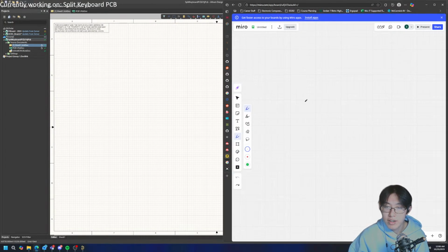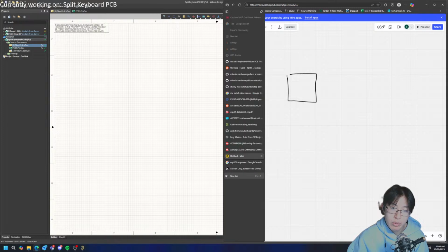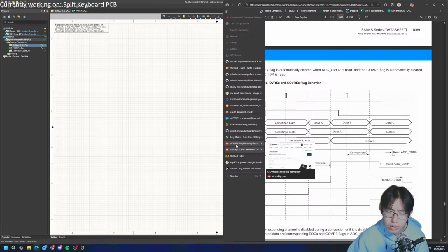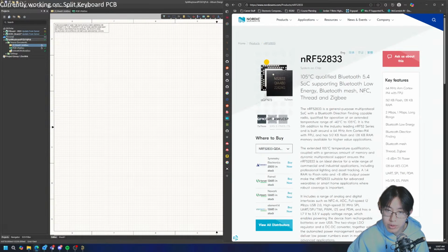Okay. All right. Then back to the drawing board. So for a wireless split keyboard, if I wanted to make my life easy, I think that the most efficient way to go about this is, so we actually have the keyboard matrix. Well, first and foremost, how many pins do we want? Because we could do 4-layer PCB. If we do 4-layer PCB, then we can go with the QFN layout.